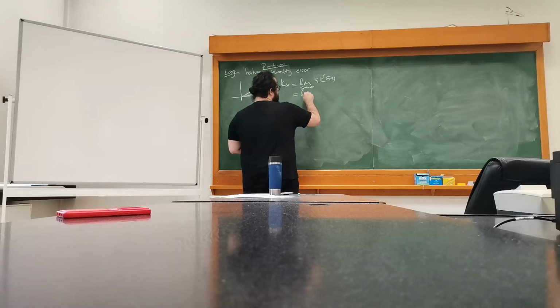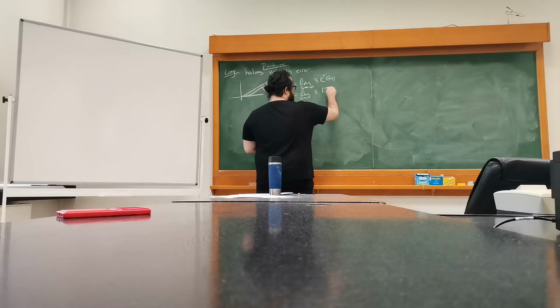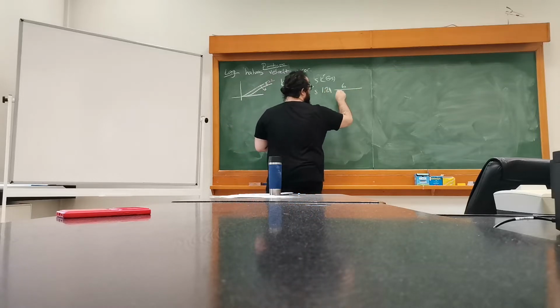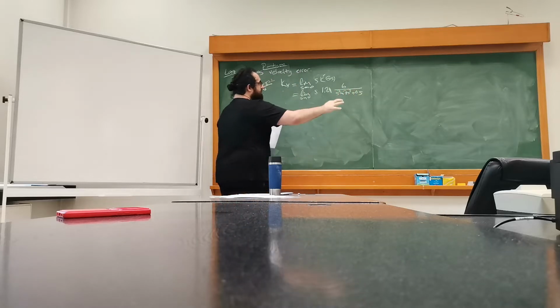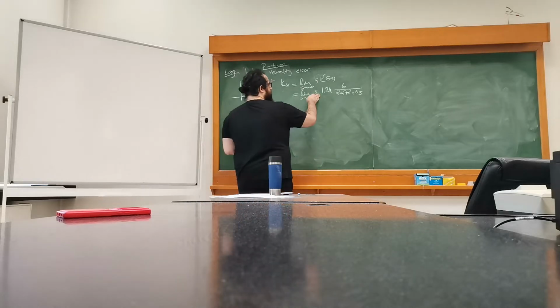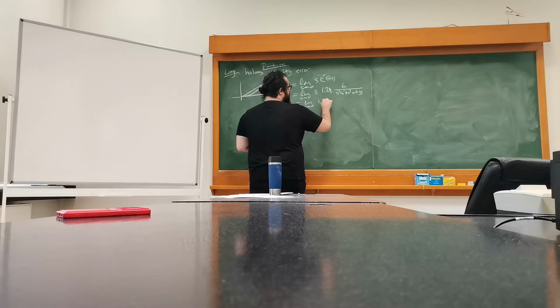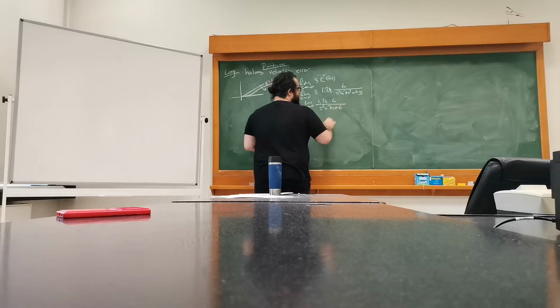So this limit is basically s times, and what is my k value that I've used? 1.24 times 6 divided by s cubed plus 7s squared plus 6s. So I've plugged in the system, the previously designed P-type controller, and I have an s term. So immediately you can see that they cancel each other out. This limit becomes 1.24 times 6 divided by s squared plus 7s plus 6.